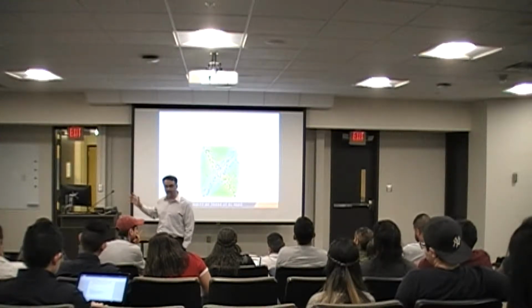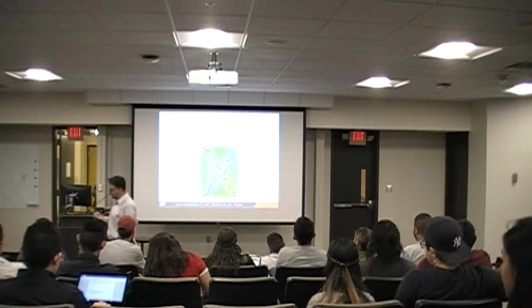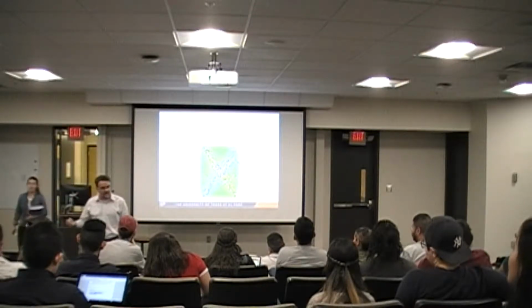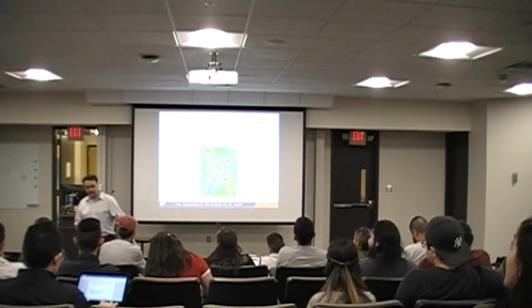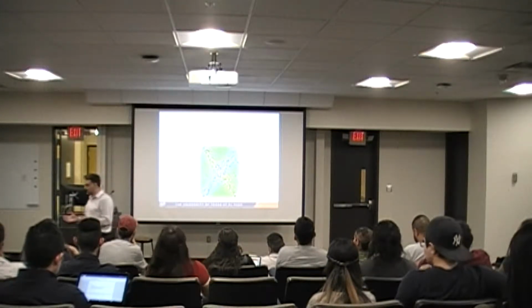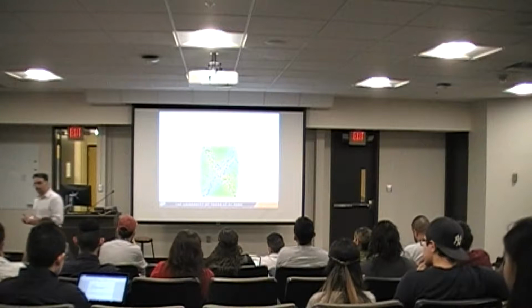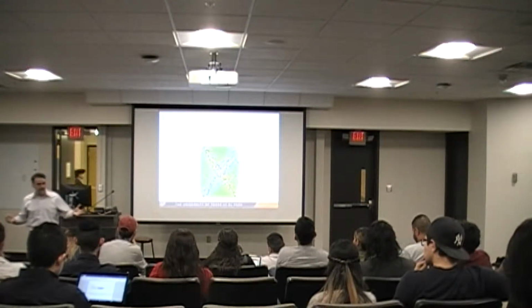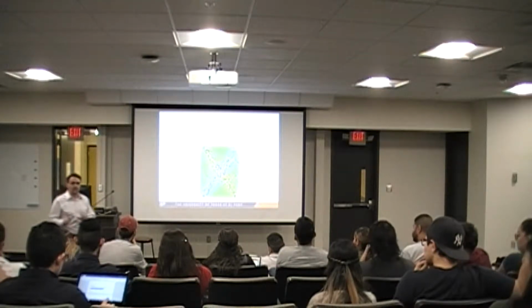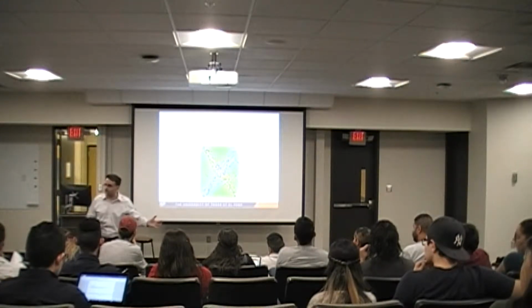So for that, we need to figure out what the shear strength capacity of our soil is. Based on that information, we can use that shear capacity in our safety factors, right? Remember we talked about the factor of safety. You figure out a measure of strength and a measure of acting stresses, and then you look at the ratio, and then you have to go and check your specifications, right?